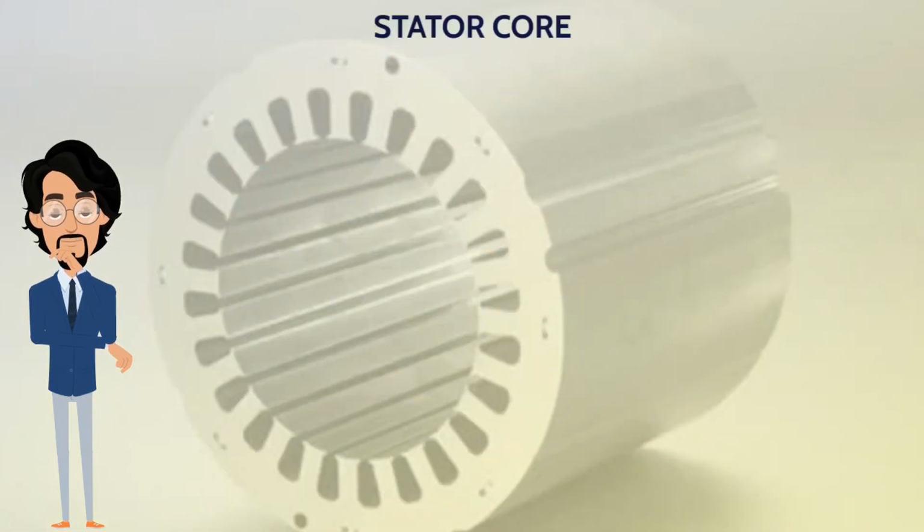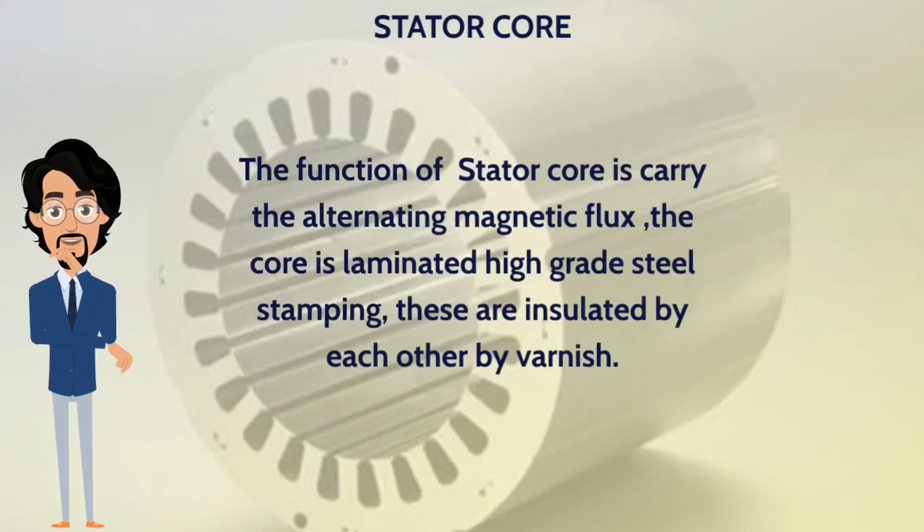Stator core. The function of the stator core is to carry the alternating magnetic flux. The core is made of laminated high-grade steel stampings. These are insulated from each other by varnish.